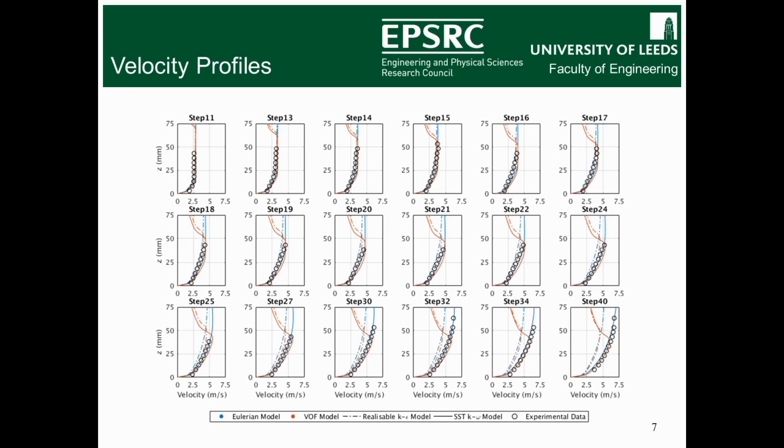It's also noticeable that with this turbulence model, the VOF model only predicts the velocities accurately up to a certain depth, and this is because it doesn't predict air entrainment, so it's underestimating the flow depth in the aerated region in the downstream part of the spillway.